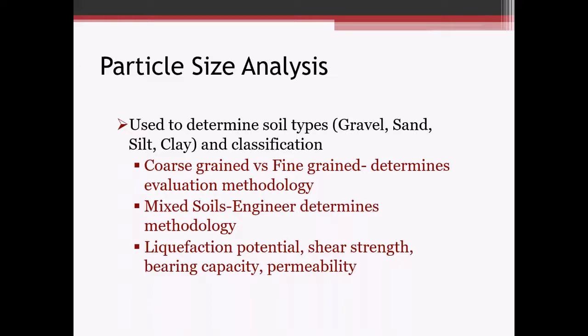If the soils are mixed, then the engineer is going to need to determine which methodology is appropriate based on how they think the soil is going to behave. If it's going to behave as coarse-grained or fine-grained soil. And it can also be used to evaluate liquefaction potential, shear strength, bearing capacity, and permeability, which I'll talk about a little bit later on in the presentation.